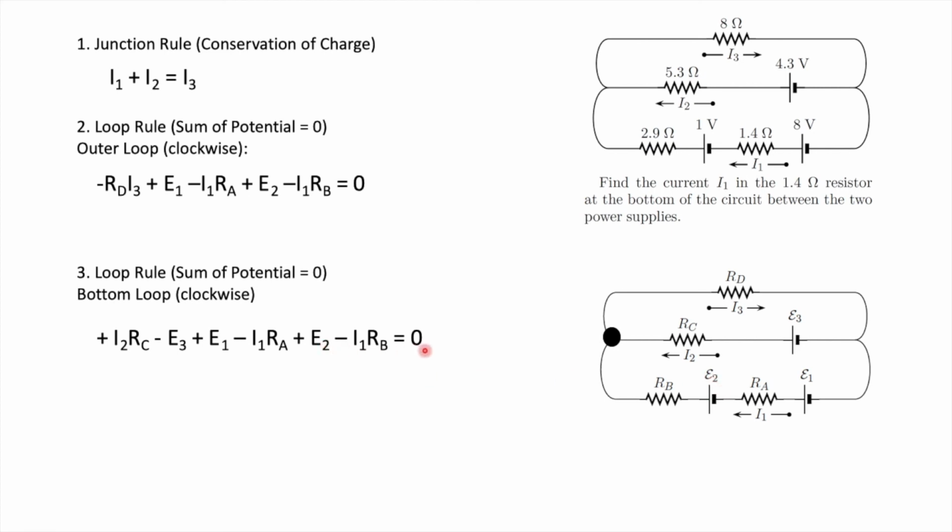So this is how you write Kirchhoff's equations, based on two rules. Again, since we need three equations to solve for three unknowns, I1, I2, and I3, we needed three equations. I have one. This is the simplest equation, only dependent on the current. But here these are coupled in resistance R and E. But all of the R and E values are known. Even here and here, all of these values are given. The only unknowns in these three equations are I1, I2, and I3.